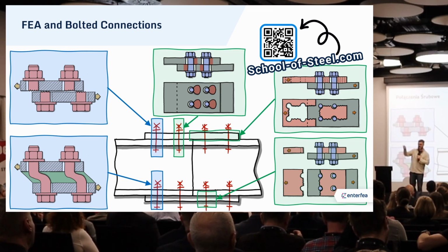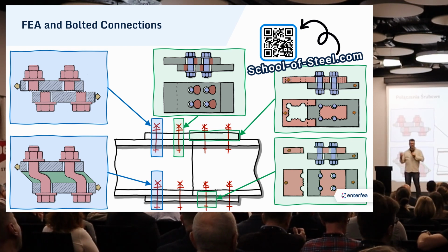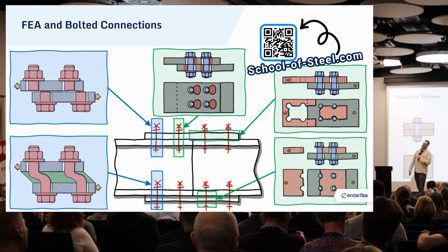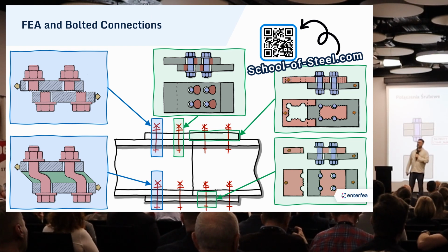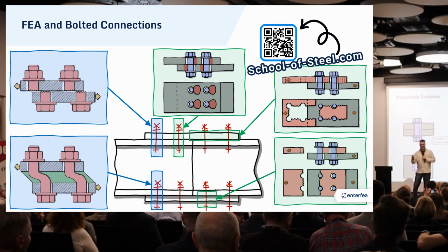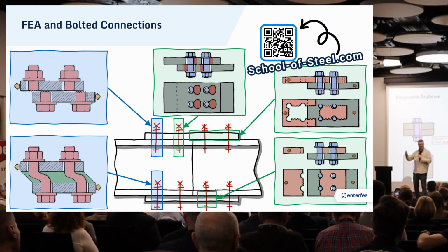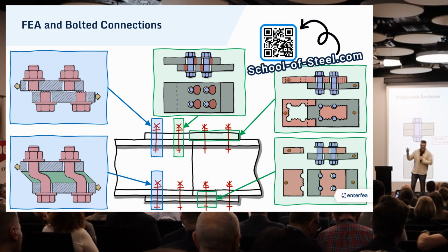And in Eurocode terms, the last one would actually be the capacity of the cross-section, but I prefer to think about it as a capacity of the connection, simply because it happens only near the connections. So I will take it into account here. And again, the ones on the left in blue simply require a decent force value in the bolt, so any bolt modeling technique would work, but those in green actually require a reasonable shear distribution. Note that reasonable shear distribution around the circumference of the opening is not uniform distribution.